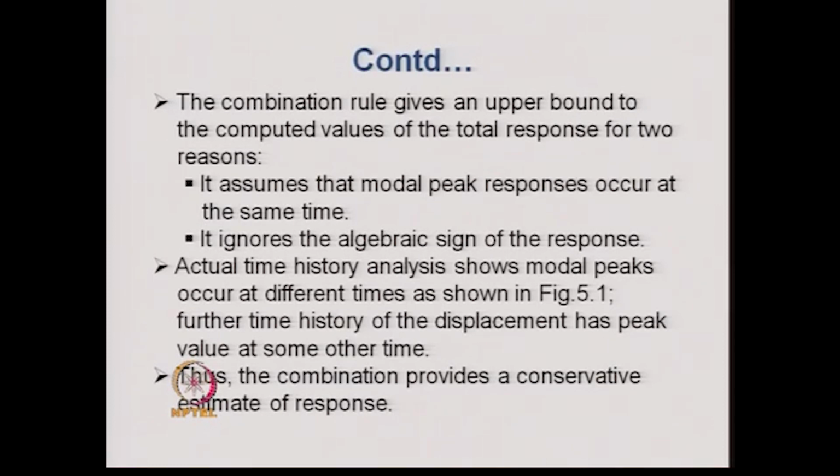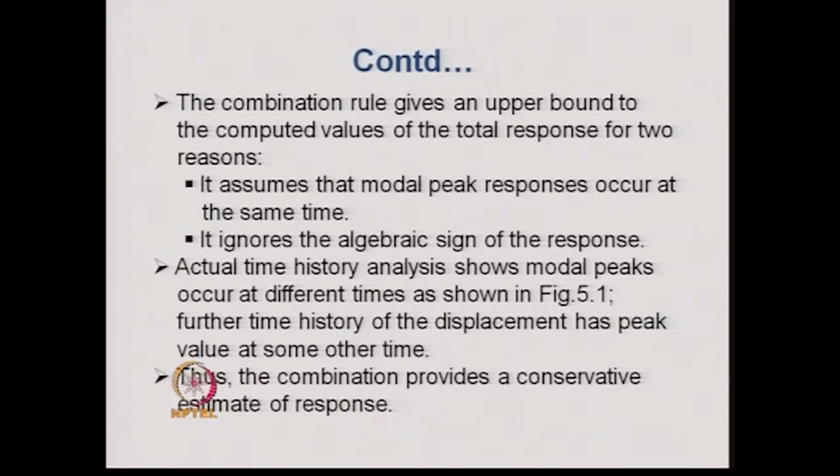For i equal to 1 to m, we will get m times at which the peak occurs, and these times will not be the same. So, if the peaks of the generalized responses in each mode do not occur at the same time, then the addition of the absolute values of the maximum responses clearly does not give the actual peak value of the response.